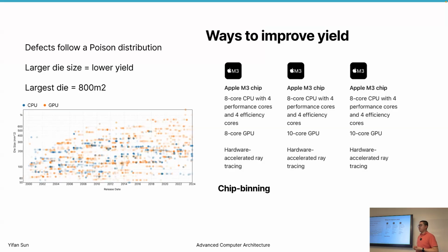And sometimes this chip binning may impact performance. Let's say these 10 cores are connected with a network, right? Maybe in this network, these 2 are closer to the center, so they're faster. These 2 are away from the center, so they're slower. Just examples. Then you buy a chip where the center one is broken, and I buy a chip where the side one is broken. So they both have a 10-core GPU, but they may have slightly different performance. That can happen.